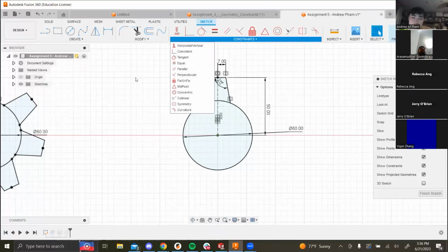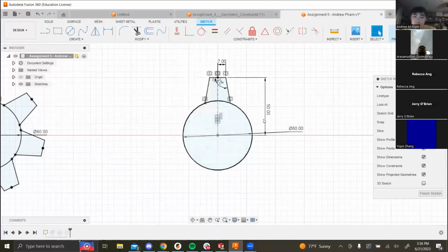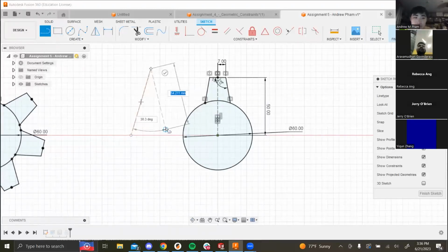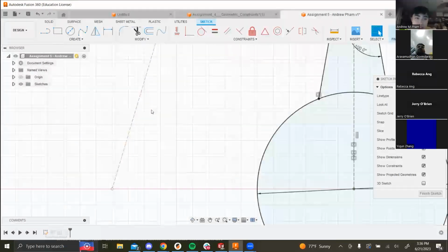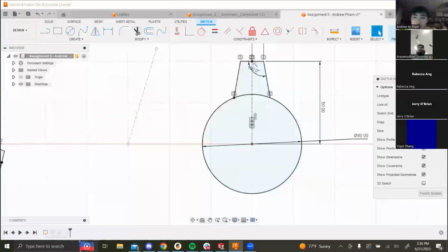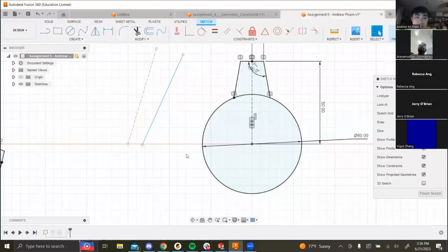Repeat how you do construction line? Yeah, sure. So this line here, you can do it in multiple ways, right? So what I like to do is I like to select construction over here when I click on the line tool, right? And then when I draw a line, you see it's dashed and not solid, right? Because when you make a regular line, it's just solid.